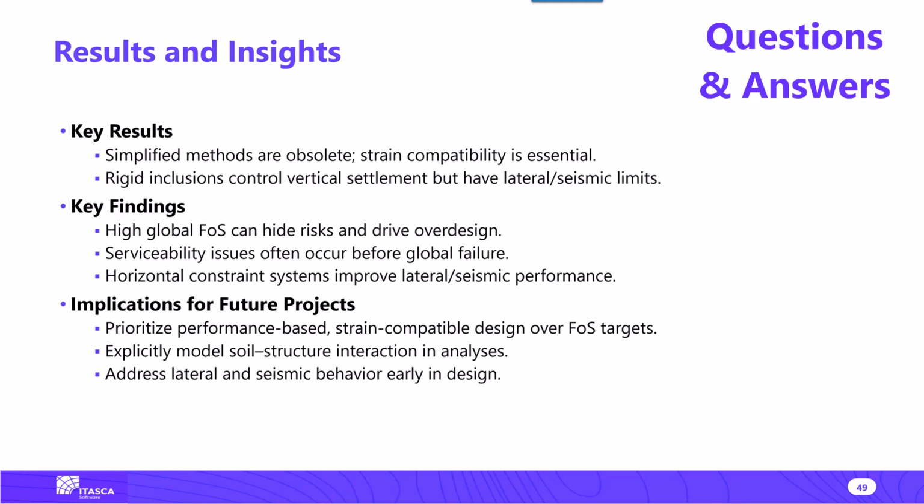Yes, one of the reasons to implement those shell elements at the top of the pile is to better capture this arching and dome effect that tends to develop. I didn't put it in my slide, but I have a slide in which I actually plot the principal stress flow, and you can clearly see the dome effect at the top of the pile.